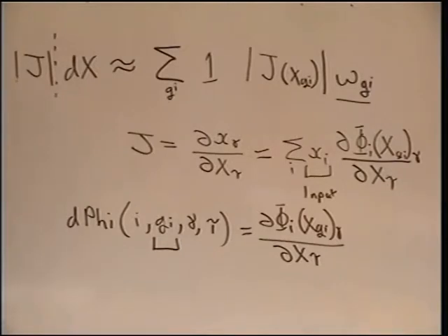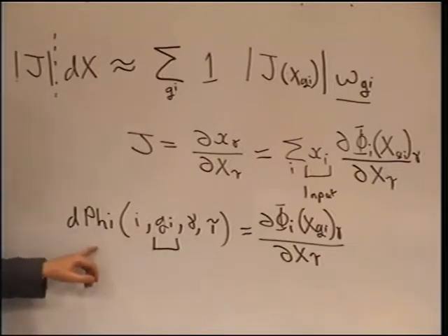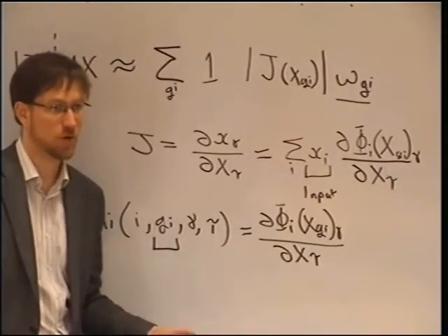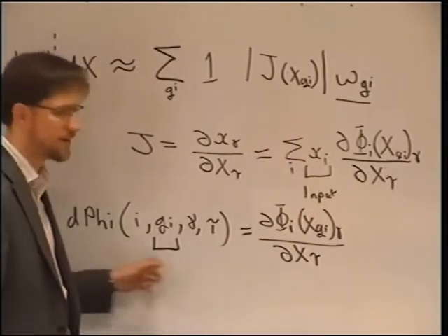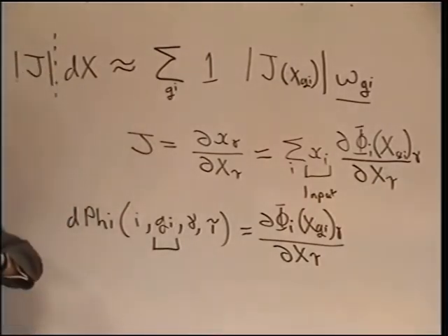And in fact, what Phoenix and therefore Firedrake currently do is they have a hard-coded assumption specifically for the Jacobian, that we know we're in the affine case, so I won't bother to write down d phi and contract it with xi. I will expand that out literally and paste it into the code. That's actually what goes on. But there's no particular reason to do that. You get exactly the same thing by backing out here. So, okay, that's that. That's how to get an integral.